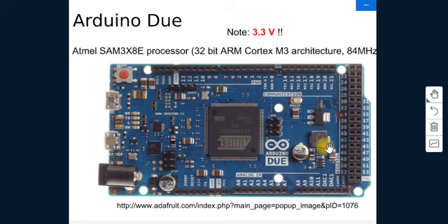So 12 PWM pins are there. And look at the transmission and receiving pairs. There are 0 to 3, meaning 4 transmission and receiving pairs. So you can communicate with 4 different devices.